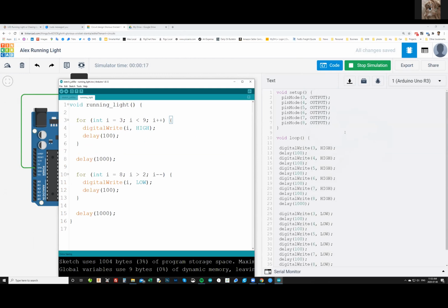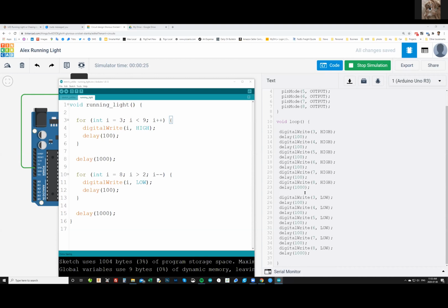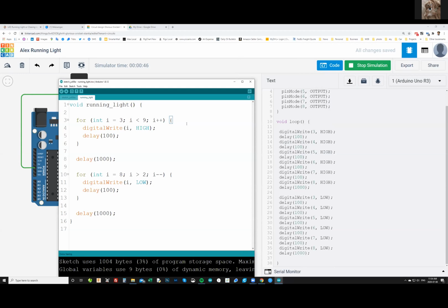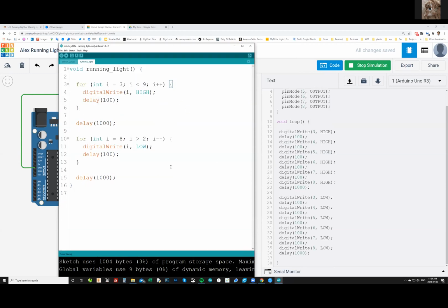Yeah, this thing on the right is macaroni because it's very similar in its structure, and it just continues on and on and on. So if we increase it to 1,000 LEDs, it's going to be 1,000 lines long every section. Every time you want to turn on all the LED strip, we have to go through each of them individually and hard code them into the code. So this is beginner programming level, and you can be more efficient. It's the same code. The only difference is just the pin number, right? Exactly. If there's any repeatability in the code, anything that keeps repeating itself over and over, you can replace it with the loop.